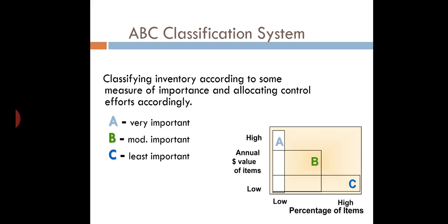Suppose you are having an automobile, and comparatively I am taking engine as a whole, transmission, engine, everything as a whole, and your other assembly parts as the secondary things. So you can take that the engine and other transmission assembly will be the A part, that is having much value, and the number will be very less. And when you consider the rivets or your nut and bolt requirement, it will be very high, but the cost is very low. That comes under the C category.